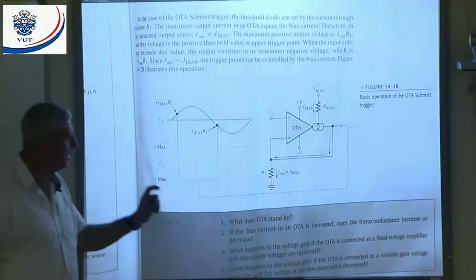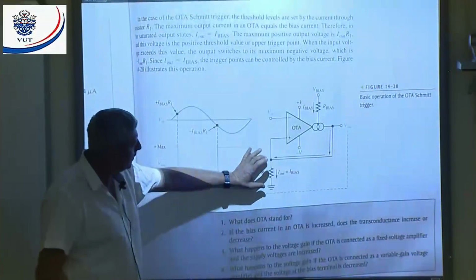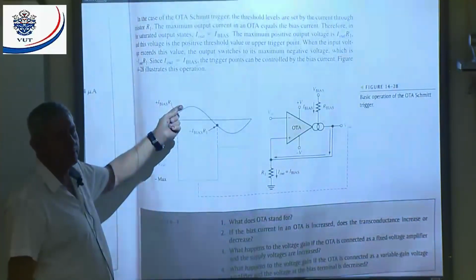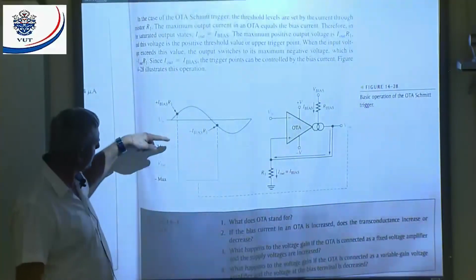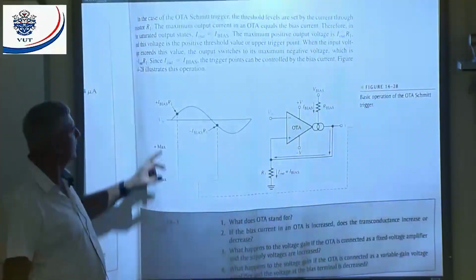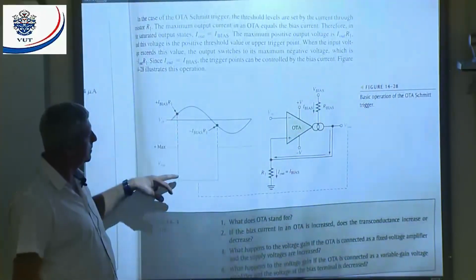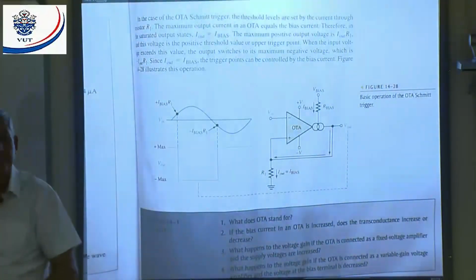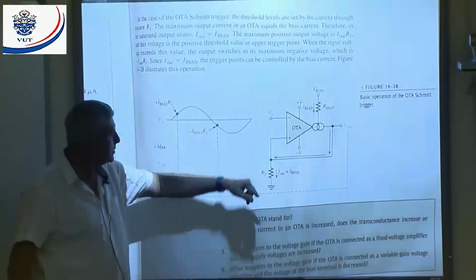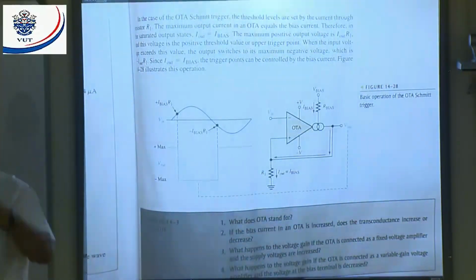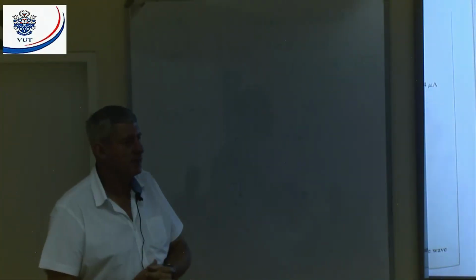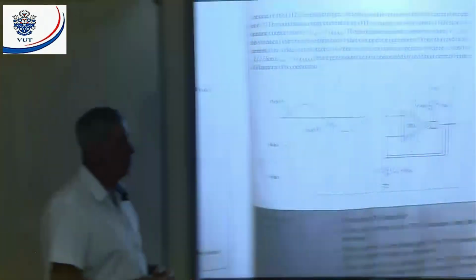But you must remember the output is positive, the voltage here is going to be positive. This input signal must go more positive or become more positive. When it becomes more positive, the output will go negative. And for that whole duration of time, it will stay negative. But here, my input signal becomes more negative than the voltage across R1. What happens then? It will go positive again. Any questions? All right, that'll be all for today.